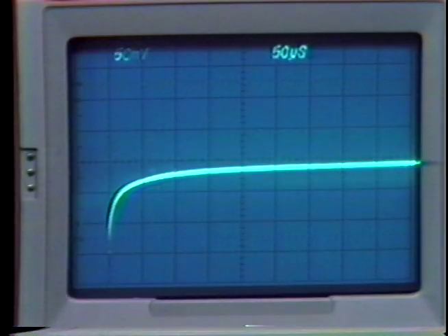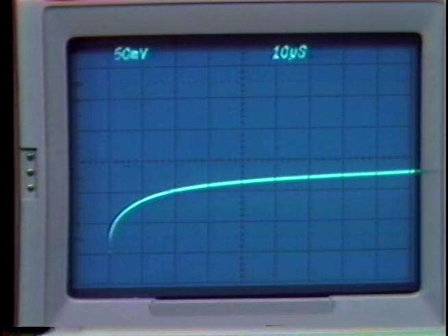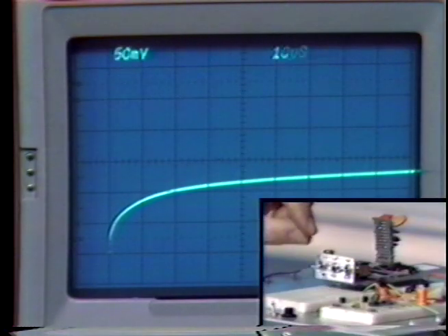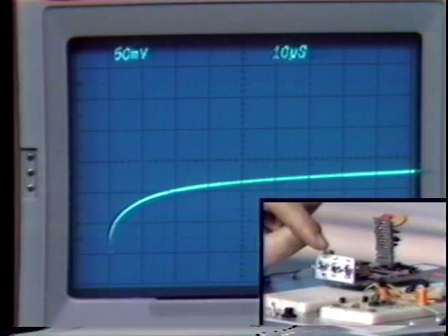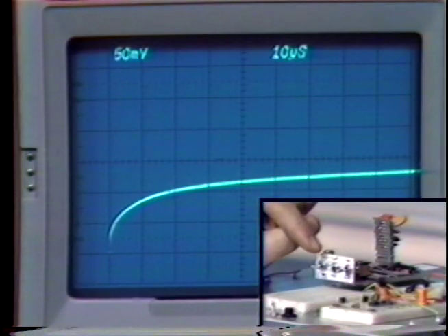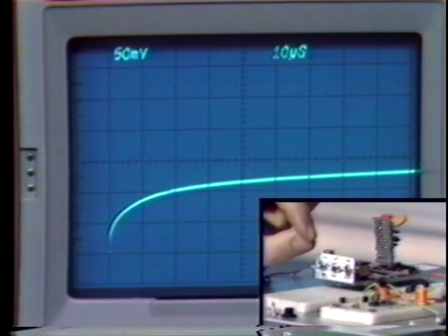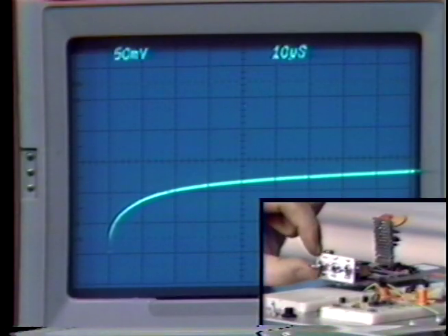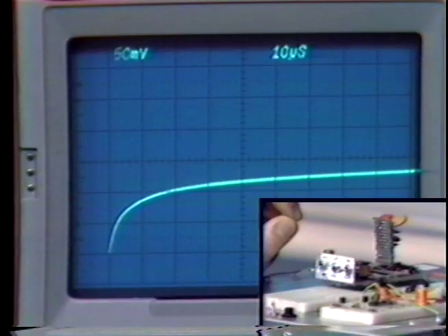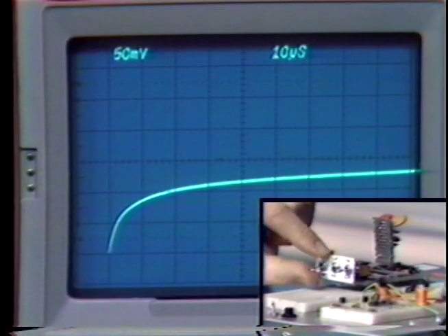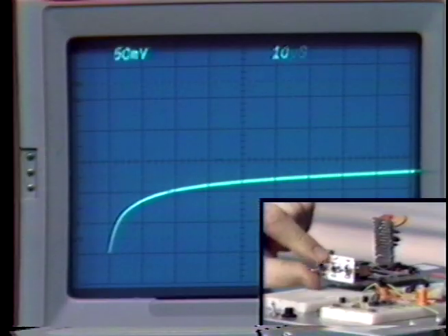And that reflects the collection of closely spaced pole zero doublets that result when this sort of compensation is used. The good news is that we get very dramatically improved stability as we add capacitive loads or an additional pole in the loop transmission. Let me first of all add the pole at 1 megahertz. Again, not much happens. That is a sufficiently high frequency so that not much changes.